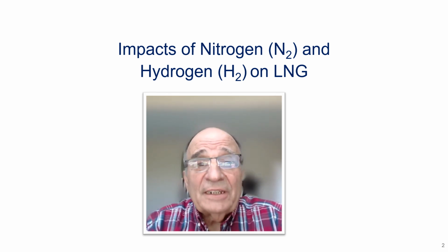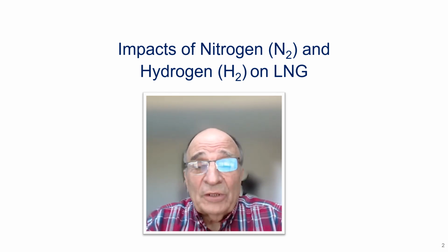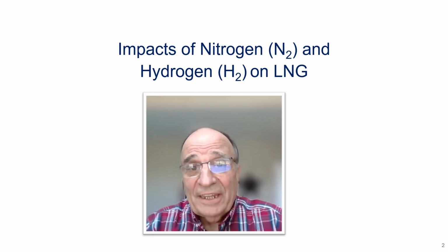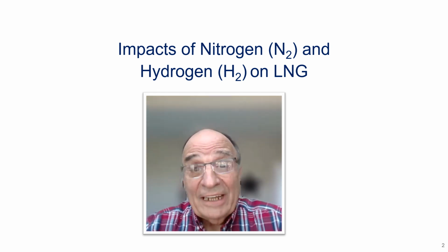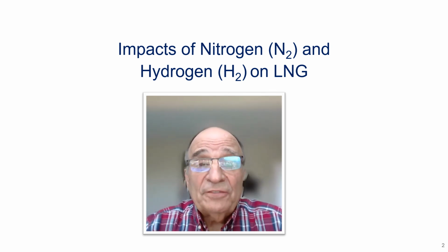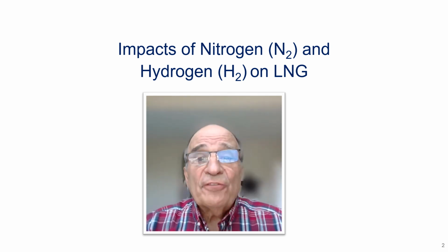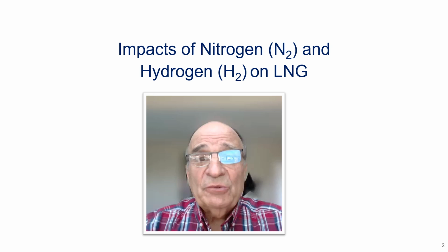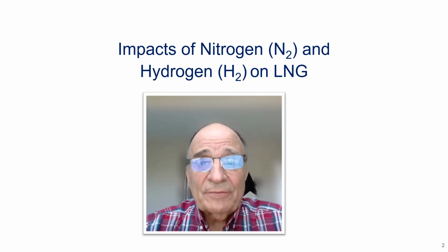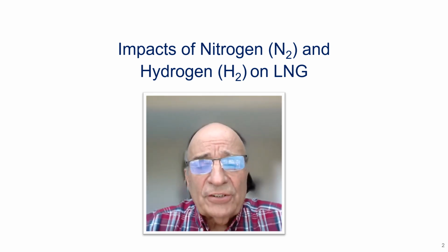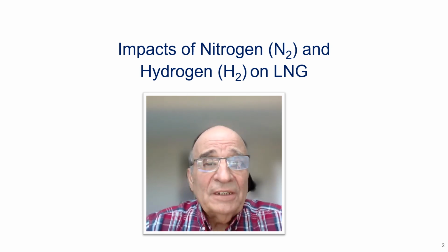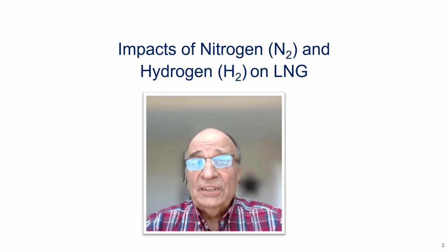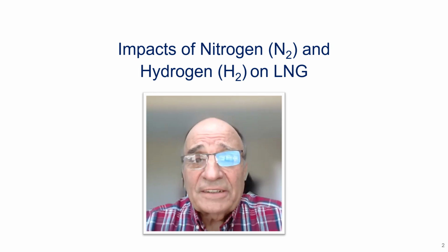Now, typically we think of LNG as being only hydrocarbons: methane, ethane, propane, etc. But we don't think of having nitrogen in LNG. But if your feed gas has nitrogen, freshly made LNG will also contain nitrogen. As far as hydrogen is concerned, historically and presently, it's not a concern in LNG because it's not in the feed gas.